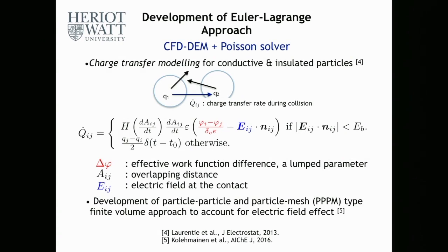And we have another parameter, this is the work function. So what is work function? Actually, work function is from solid state physics. The minimum energy needed to pick up 1 electron from your material into a vacuum. So we use here an effective work function because we would like to use this one for the dielectric materials also. This is a lumped parameter. We use our experimental data to determine it, or we use some quantum mechanics calculations. And here also the third parameter is the electric field.